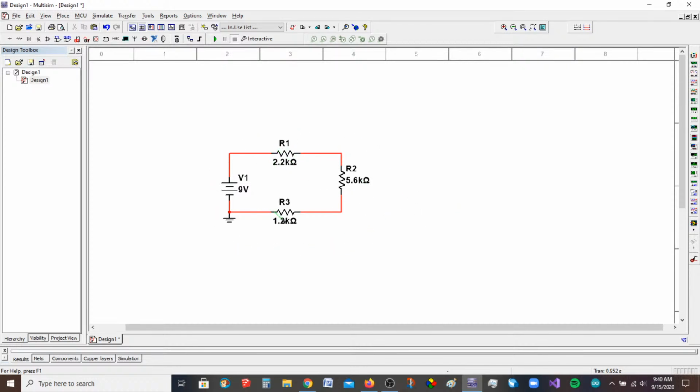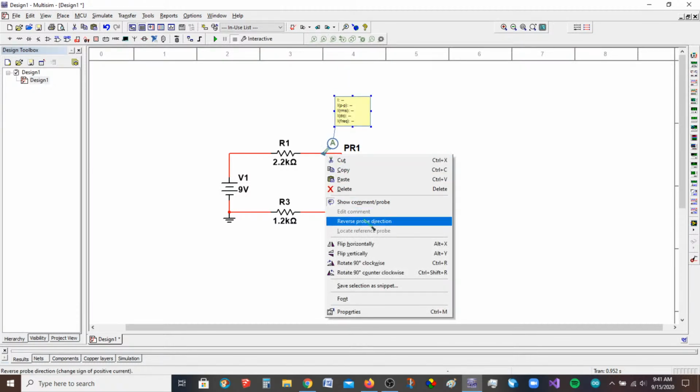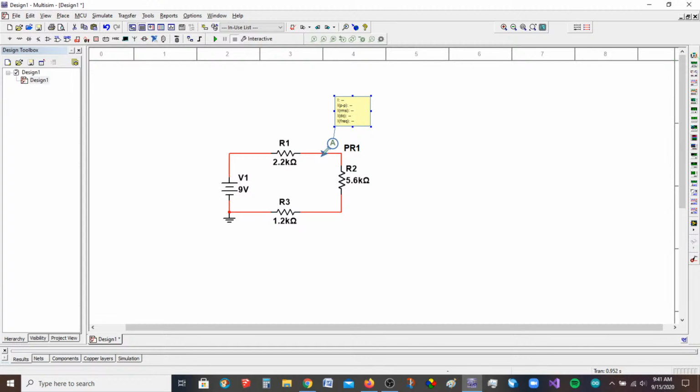I find the total resistance, I find the total current, and then I can find the individual voltage drops, right? So I get all my work done, and I say, I wonder if I got this correct or not. Okay, you can just come in here and start measuring the current. Let me flip this around. You can measure each of the component values.